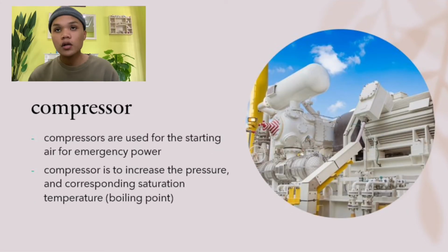Okay, the function of the compressor is to increase the pressure and corresponding saturation temperature, which is the boiling point, of the refrigerant vapor to a high enough level so the refrigerant can condense by rejecting its heat through the condenser.